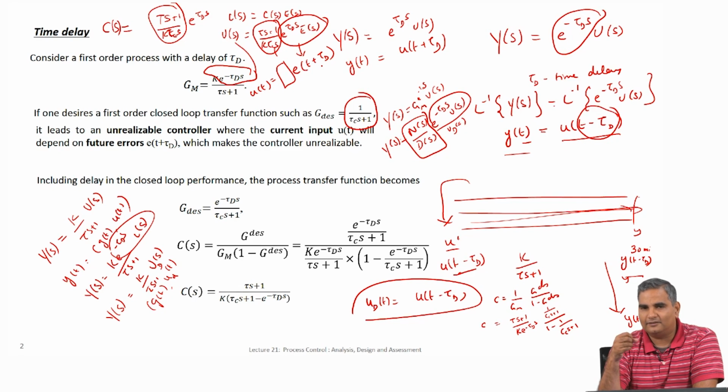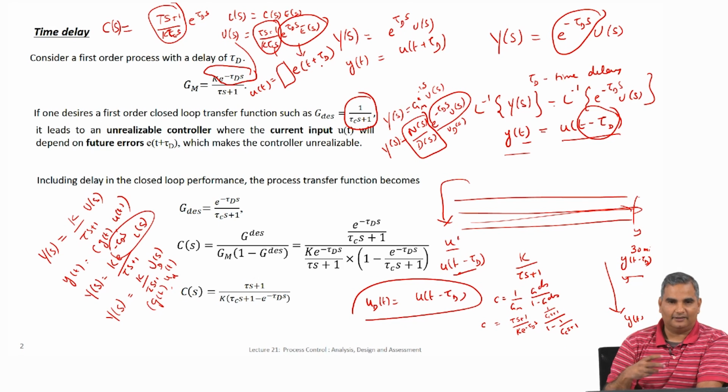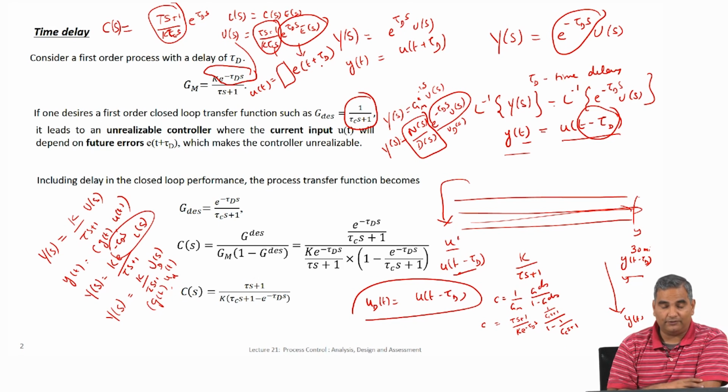So you see why this time delay creates problems in control, because you have taken an action and you really do not know how long you have to wait, because you cannot get a very good estimate of the time delay at all times, right. So you just have to wait, and you do not know whether it is really that you have not opened the knob enough, because of which the water has not become hot, or whether, because of time delay, if you have opened the knob enough and you wait for long enough, you will get hot water. So it is a very interesting question, and it makes the controller design that much more complicated, particularly if you do not have a very good idea of how long the delay is and so on.